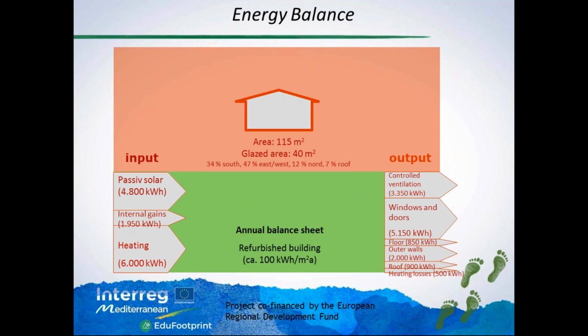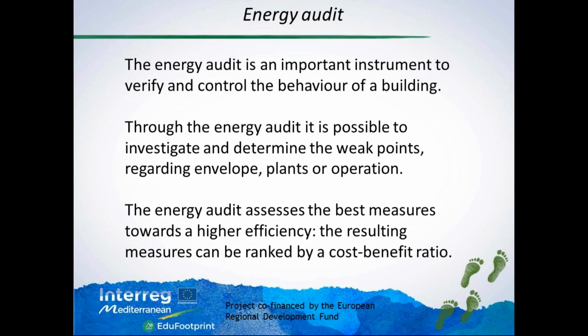And to make some intervention, it's important to make an energy audit. The energy audit is the tool, the instrument we have to decide, to have a strategic plan for the refurbishment of a building. Through the energy audit, we try to describe, to replicate the behavior of the building through the year, and to calculate the savings that some hypothetical measure can bring.